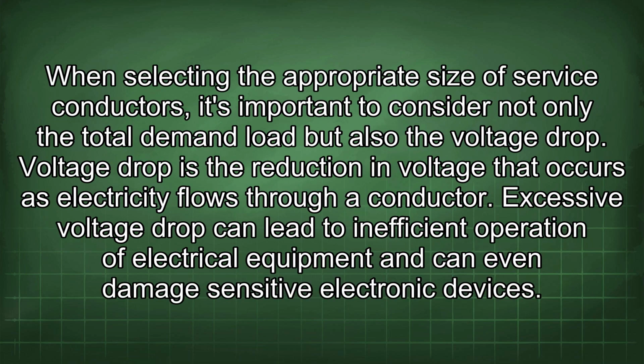When selecting the appropriate size of service conductors, it's important to consider not only the total demand load but also the voltage drop. Voltage drop is the reduction in voltage that occurs as electricity flows through a conductor. Excessive voltage drop can lead to inefficient operation of electrical equipment and can even damage sensitive electronic devices.